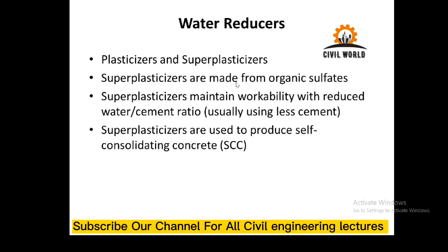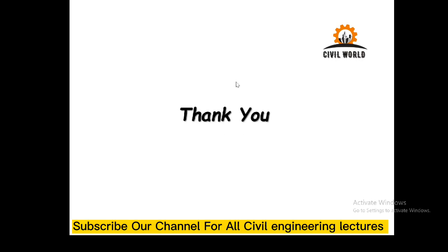Normally, plasticizer reduces water requirement by around 15%, and superplasticizer reduces the water requirement for concreting by around 30 to 40%. So with this, we come to the end of today's lecture.